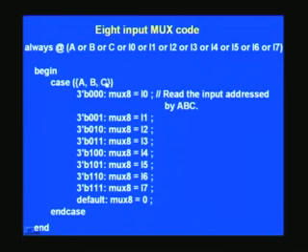That means to say a single signal can be put here, or any other multiple, even a statement can be put here, right? And so what all this means is, when ABC each of them is 0, corresponding to this, what we should get is I0 at the output, right? And similarly, if it changes for different values, let us say 111, naturally I7 must be selected and output to the mux 8. So it is as simple as that.